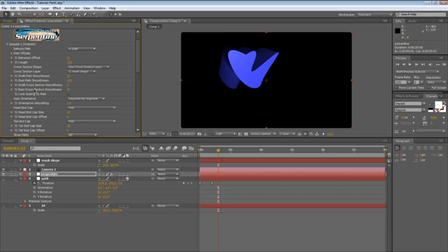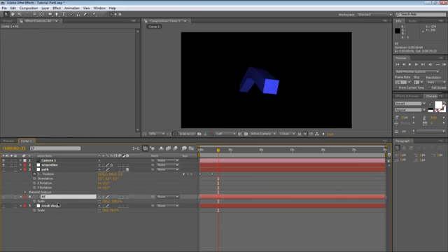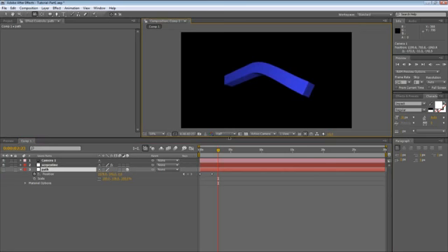And here's another thing you can do, a really cool thing. Let's just go back to just a simple rectangle for this. I'm going to show you what scaling and Z rotation can do to your serpent, which is really cool. Let's delete these two layers. Let's start with scaling. So let's change the camera angle a bit, and let's say that from the beginning of the path, the scale of the solid will be really small.